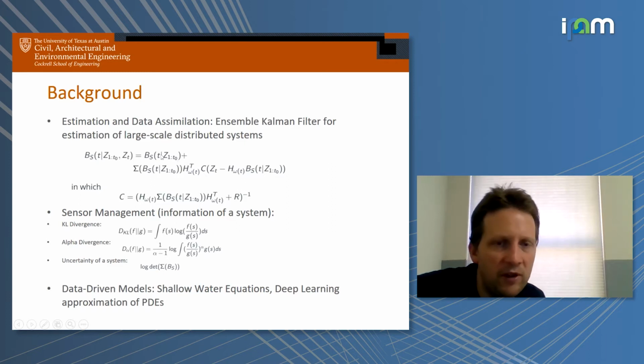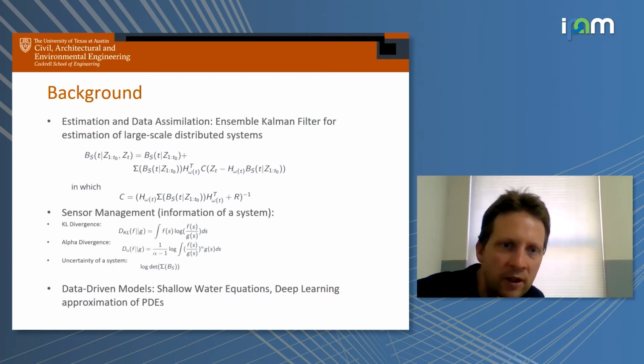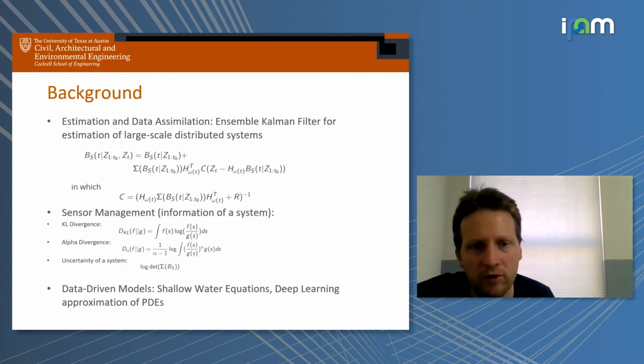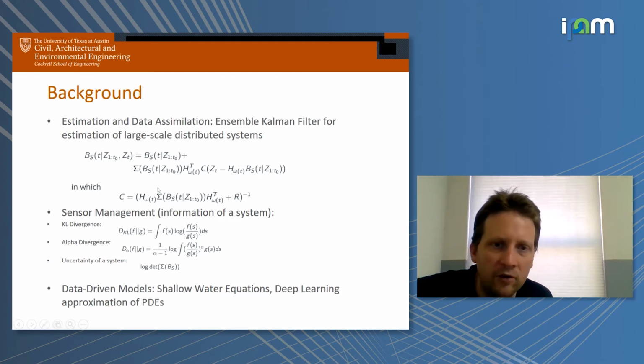We take the prior estimated states and we add information to this, so it's a classical thing. You take the observation matrix and multiply it by the difference between the measurements that you're getting minus the predicted measurements that you are supposed to get. That's the innovation part. And of course, the multiplication of that is the Kalman gain, which depends on how you configure your uncertainty: what is the covariance of your state, and what is the measurement covariance, so the covariance of your sensor measurements. That's the estimation data assimilation step, the classical Kalman filter formulation.